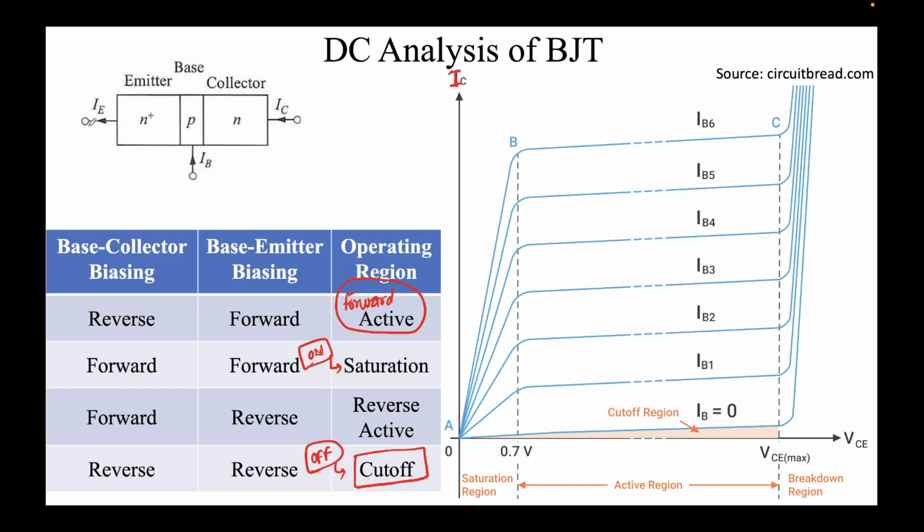So essentially, what you can think of it is something like this: that there are different biases. I'll draw this. So this is, let's say, the forward bias, but this bias can change. This is VBE, and this is VBC. So this VBE and VBC is the biasing that I've written here, so they will change. When both of these junctions are reverse biased, you are operating in this region, and you can see very little current is flowing, no matter how high a VCE you choose. Current is not even flowing, right?